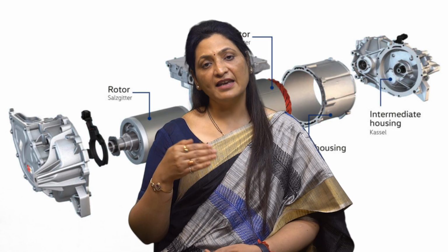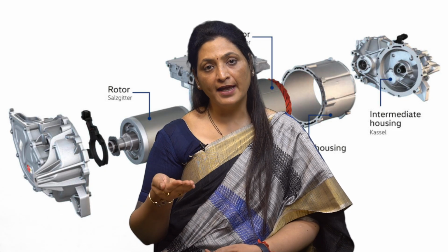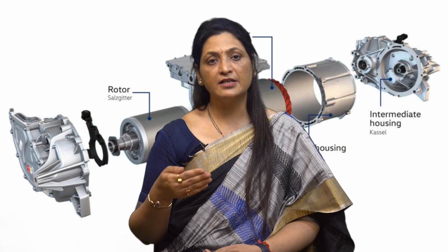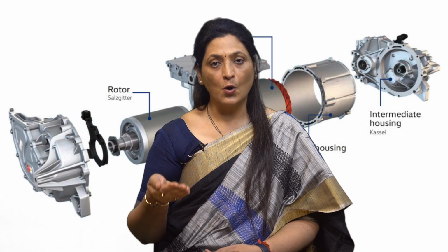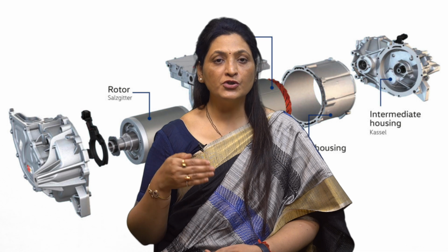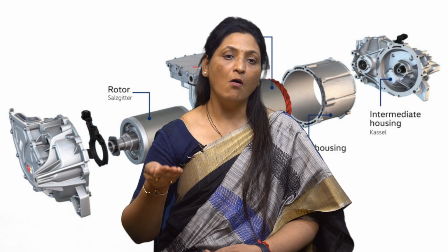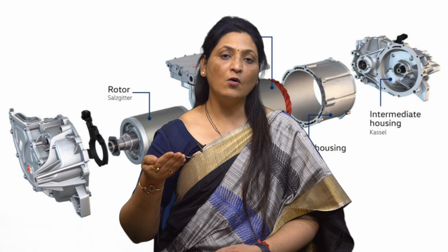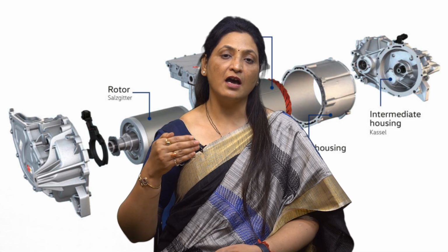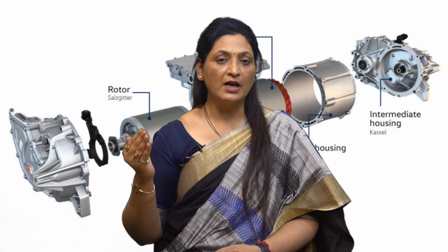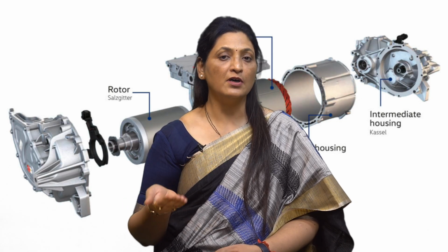Then the mechanical considerations such as type of enclosures, type of bearings, transmission of drive, noise level are also crucial during selection. Lastly, after taking into account all the factors, the capital cost and running cost are also taken into consideration for the selection of the motor.